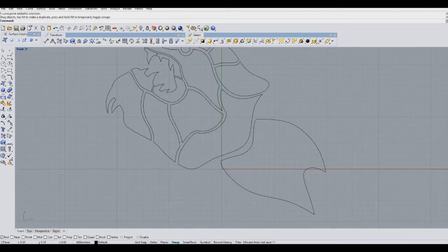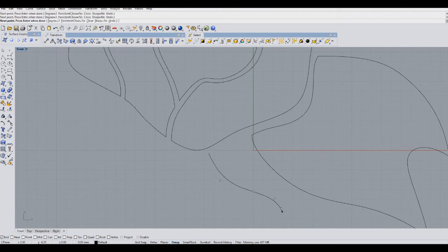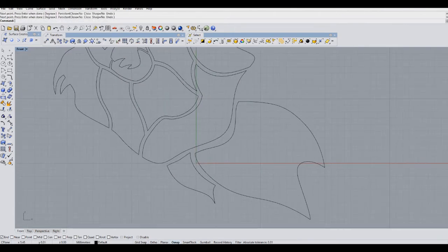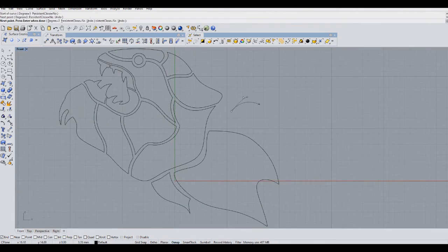Going back to the topic of switching to a new version of the Rhino software, overall it was not really a big adjustment. I had to deal with a couple new features, like the thing with curves that you could probably see in the footage here. When I draw a curve and then I put it down on the surface, one feature that 6 has that 4 didn't is if I click on it, it assigns the control points automatically to either an open or closed curve just by selecting it.